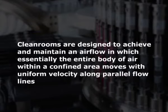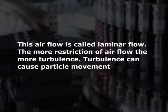The next is clean rooms. Clean rooms are designed to achieve and maintain an airflow in which essentially the entire body of the air within a confined area moves with uniform velocity along parallel flow lines. This airflow is called laminar flow. The more restriction of airflow, the more turbulence. Turbulence can cause particle movement.